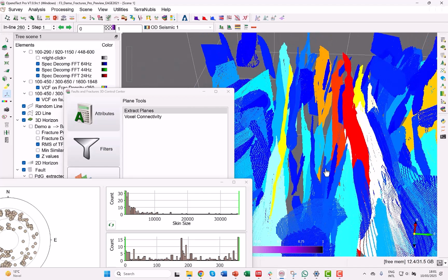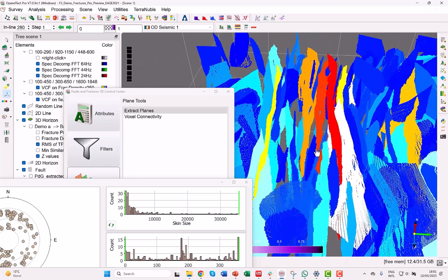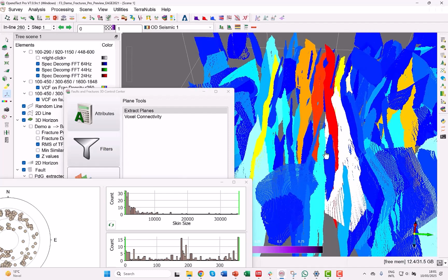In seismic interpretation software, a fault plane is basically a collection of fault sticks which are then interpolated to create a fault plane. So if I want to convert this into a fault plane that I can also use in other software, I have to extract these and sample them with fault sticks so that they can then become fault planes and be used in other software.